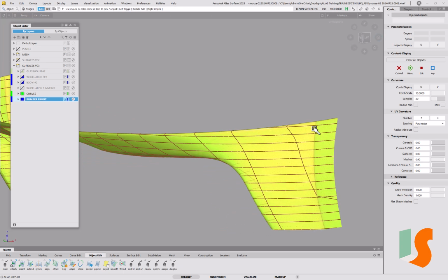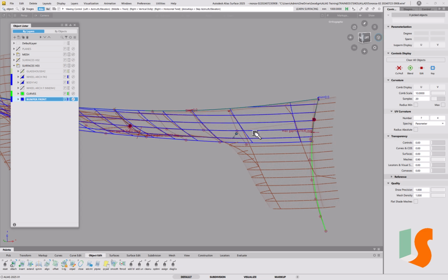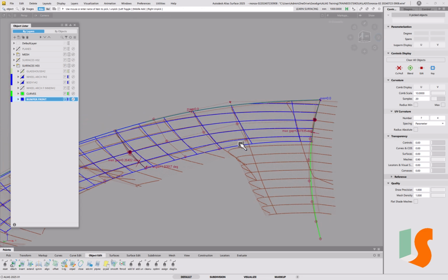and it's very important that we keep that sort of line, I think, more than keeping, especially when we deviate it from the data, we've got to keep that line in the front view, which it is very difficult to see where that is, to be honest, because you can see, you know, it's very, very subtle here, it's somewhere around here, and then over here it's a bit clearer that there's going to be an edge across here. So I think in an area like this, what I would do is throw the surfaces in on here, and then throw a surface in on here, and then see where they cross over. It's going to be a wobbly line, of course, when we do that, but then we can work on smoothing that out and trying to get something like the character of the original.